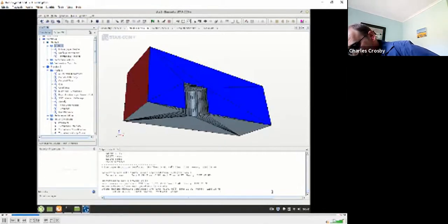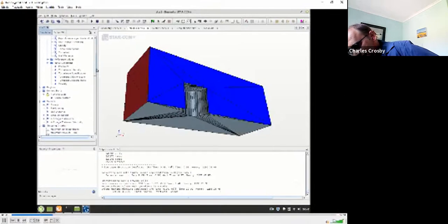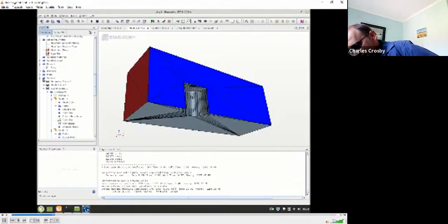We've used exactly the same size settings as we did with the previous mesh, but you'll see that it's a mesh with far more cells. It's now 452,000 cells. Let's update our mesh scene, because at the moment we've got it as a surface mesh representation.